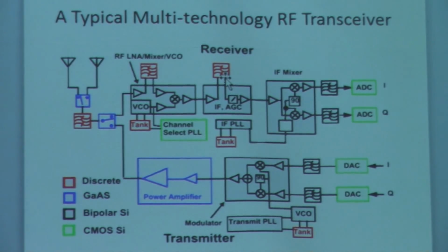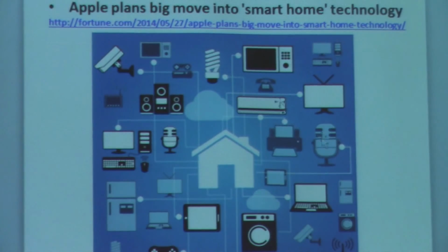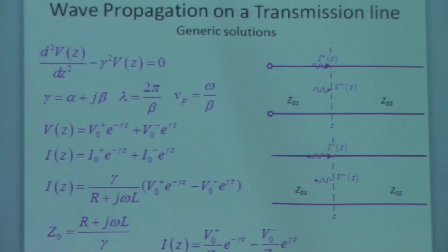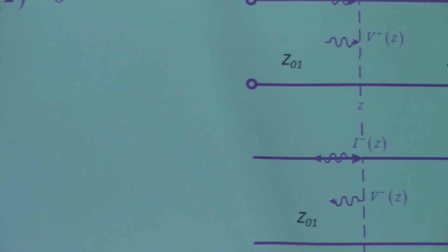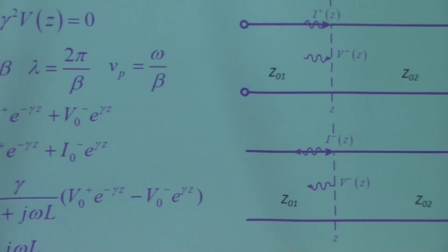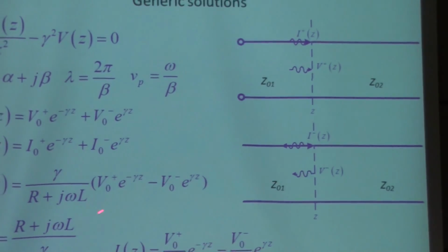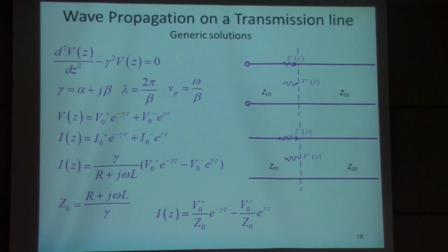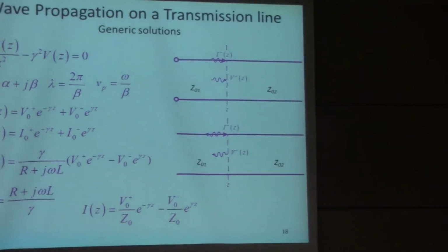That's because we need that filter. Otherwise, it's a mess. Filter design is related to high-frequency signal propagation, and very often you start from this gamma. You control the gamma. In other words, you control the dispersion relationship I just mentioned. The gamma has the beta, and you have the omega, and you control that.